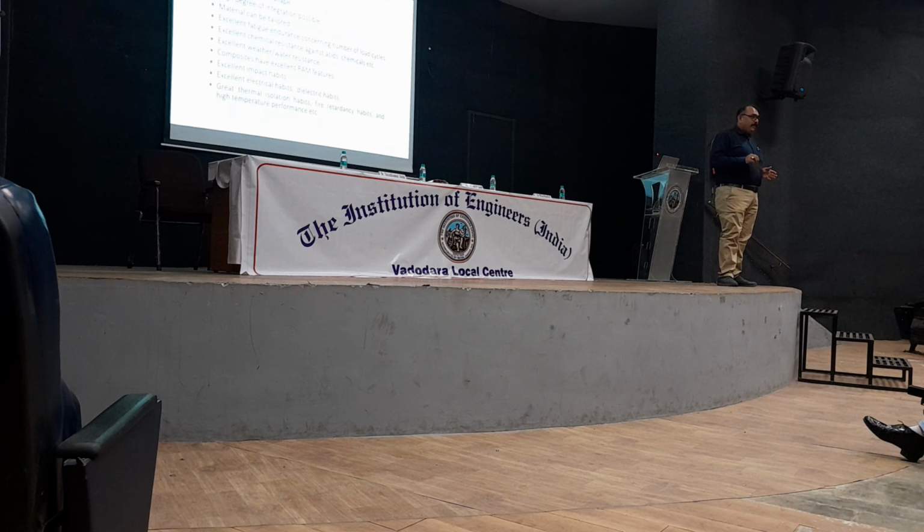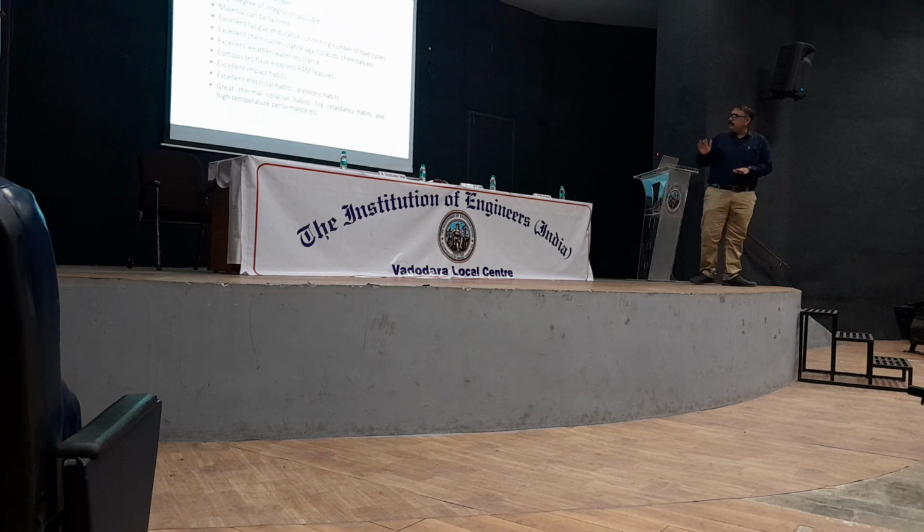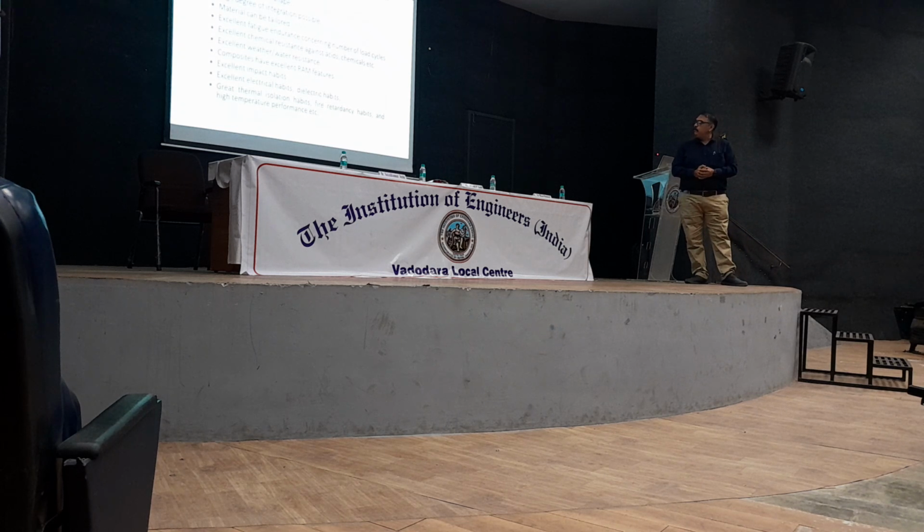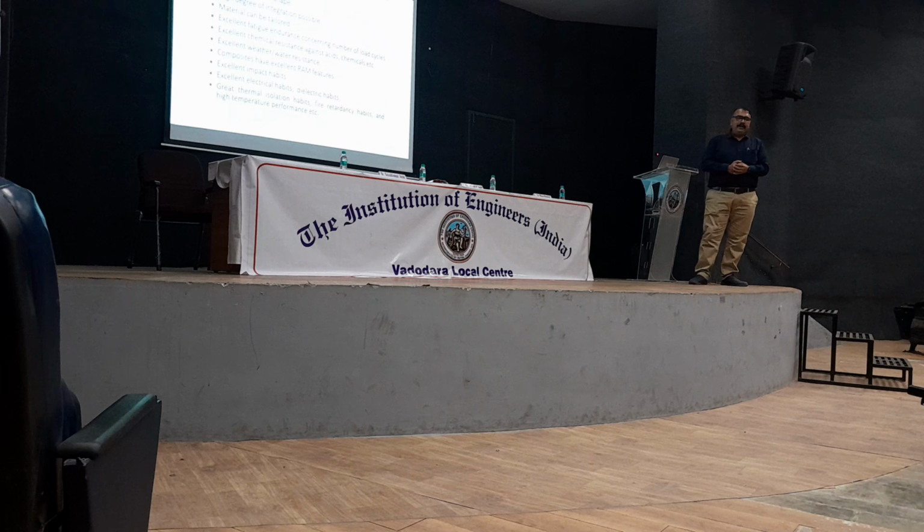But at the same time, here with the fibers and other things, we have to see how easily they are available and how we are laying down the patterns. So that is very, very important. So great freedom of shape. Then a high degree of integration is possible. Whatever insertion or any development is required, we can incorporate. Material can be tailored. Excellent fatigue endurance concerning number of load cycles. That is, under variable stress it is good compared to other materials of the same weight.